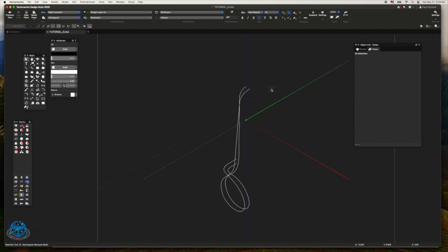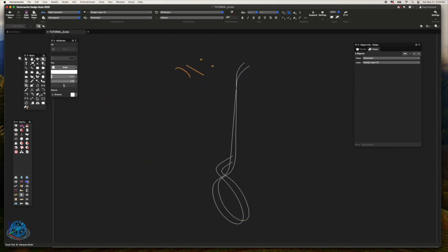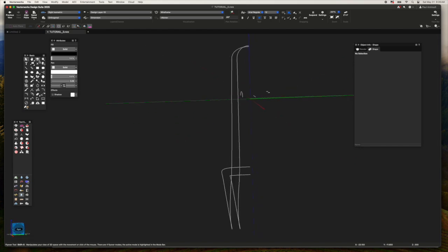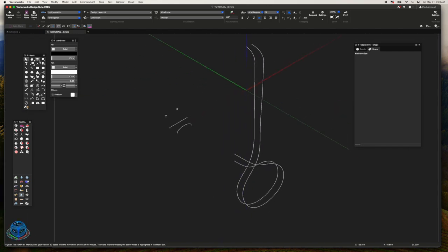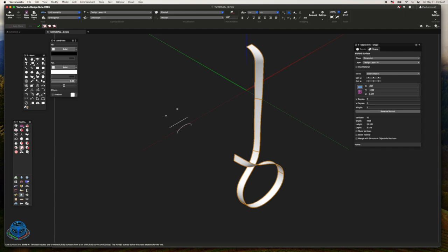So now I'm going to introduce some friends here. We've got two NURBS curves and just two ordinary planar circles. We'll start with the NURBS curves first. But before that, I can create basically my shape by just using loft surface. It's going to give me a flat curve, and then using the shell tool, I can shell it to a thickness.